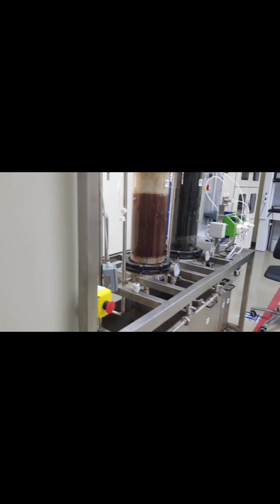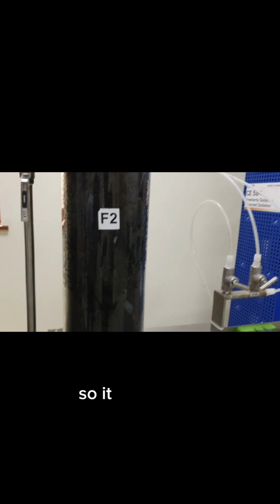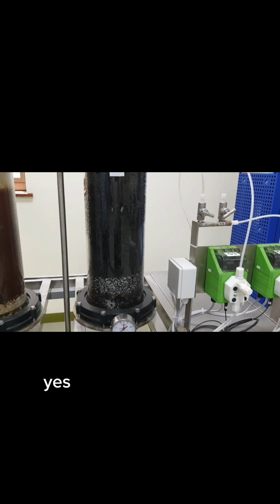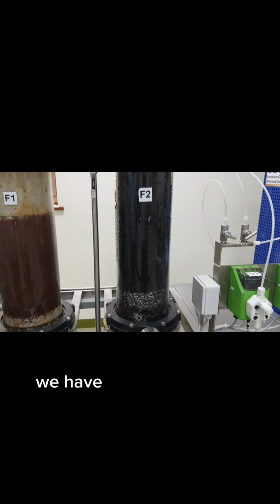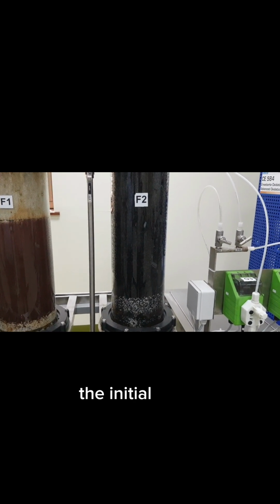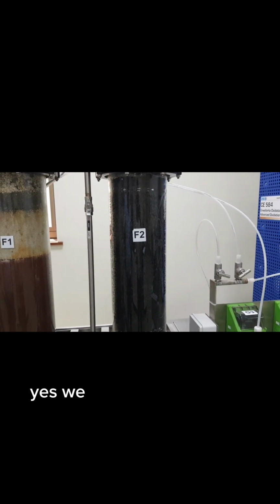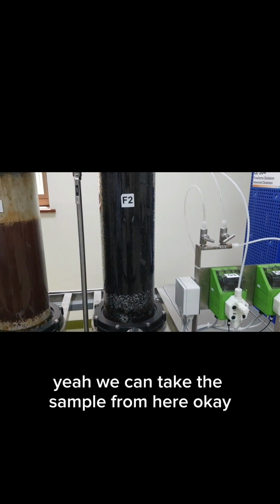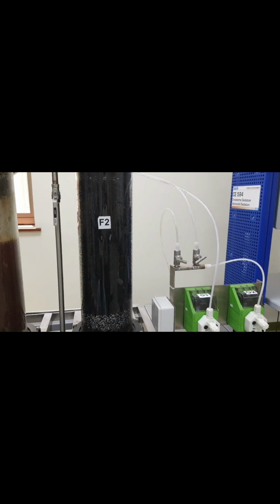Let me check it. Yeah, the water is flowing. Yes, right now it is still here. It's flowing, coming to the column. And how to take the water? We have to take the initial water, Mr. Gulrez, for analysis. Initial water means at time 0. Yes, we can take the sample from here. After every 5 or 10 minutes, we will take the sample and then we will analyze for chloride.